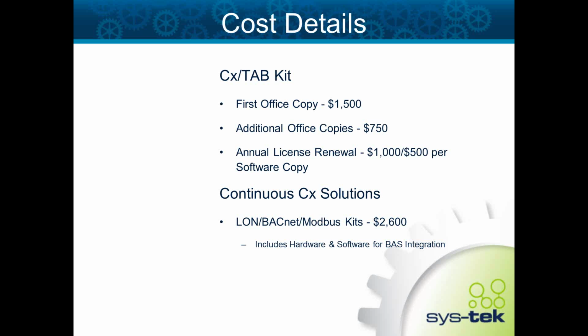For the continuous commissioning solutions, we have standard kits that you can buy that are developed to access LAN workspace systems, BACnet, and Modbus-based automation systems or power monitoring systems, whatever the application may be. The nice part of the Tritium side of it is we also have access to proprietary software protocols, for example, like Johnson Controls N2 protocol or Carrier's Comfort Network. So we can provide software drivers for those as well.